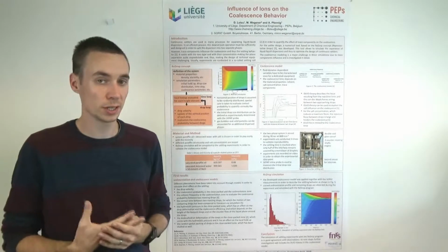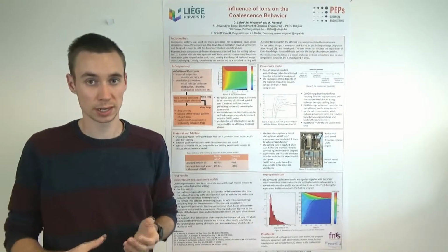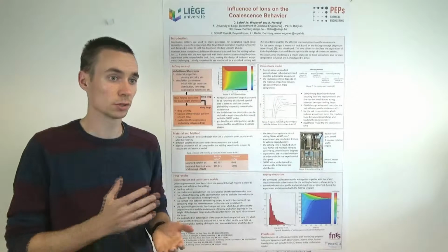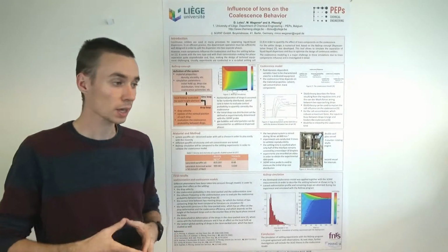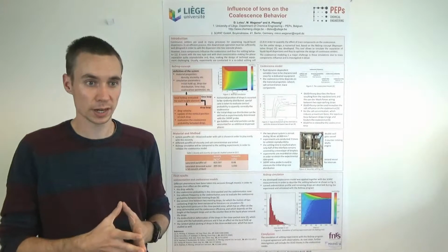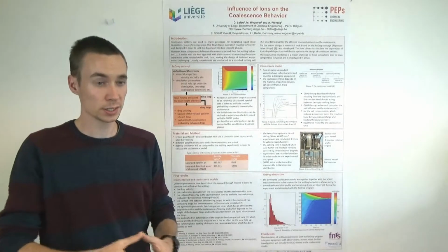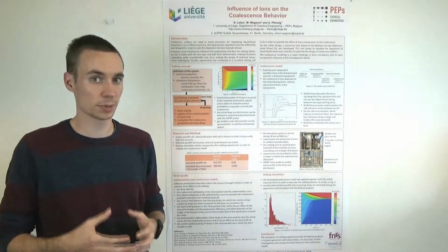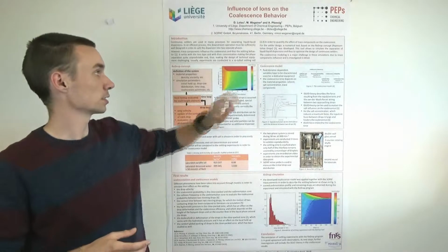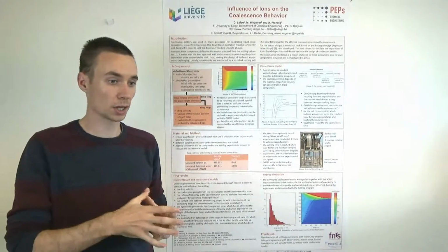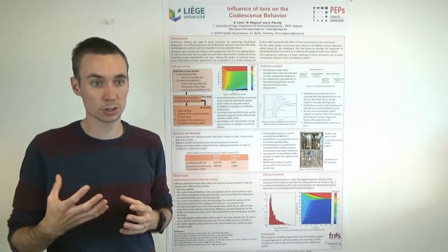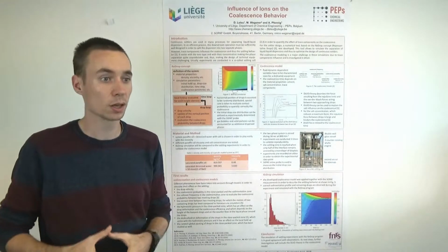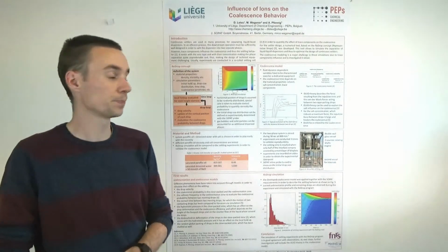However, coalescence is really influenced by trace components and impurities like salt. So if you add a small amount of salt in your system, the coalescence behavior will change, so the design of your equipment will change. And as it's difficult to quantify the influence of these impurities, an experiment has to be done in order to characterize the system. This experiment can be done in a settling cell. Then, from this characterization, you can use a simulation tool to optimize the design of your equipment. And in this simulation, the challenge is focused on the coalescence model.